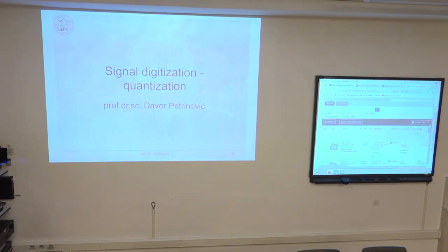And you have to measure this very small charge, some picocoulombs, by selecting column, selecting row, and sending this value to the AD converter. This AD converter must be capable of converting the whole image, the whole megapixel resolution, 120 times per second, or 60 times per second.